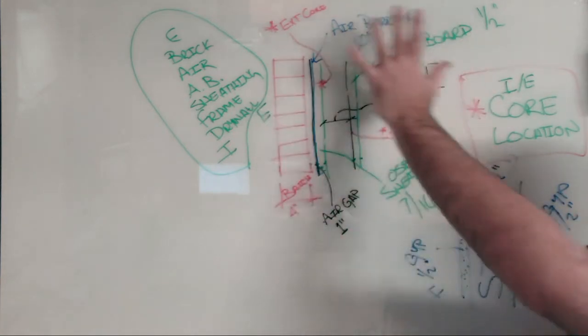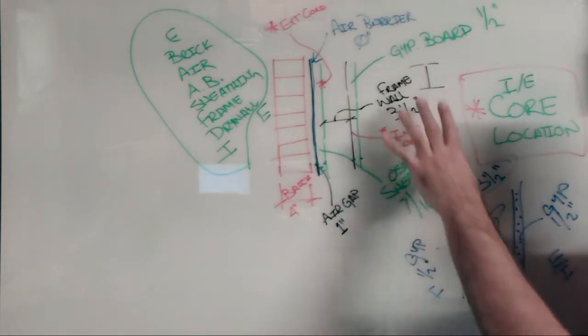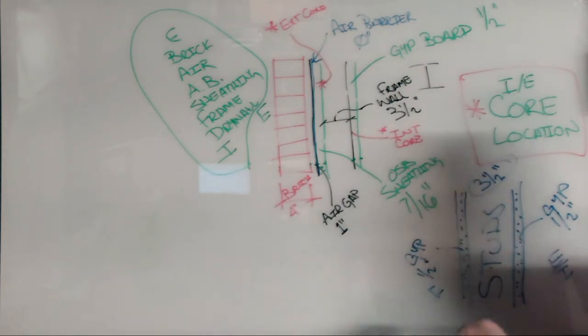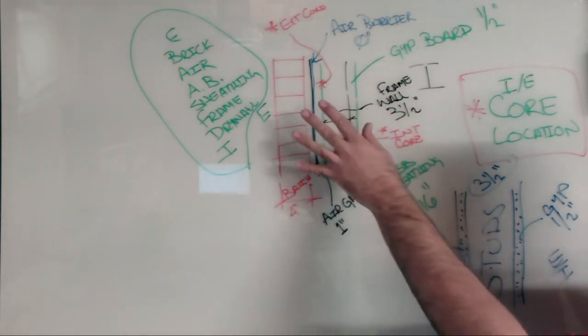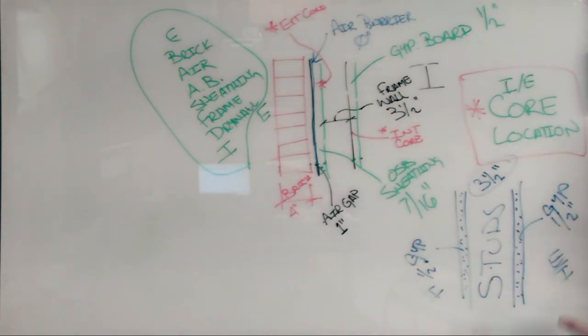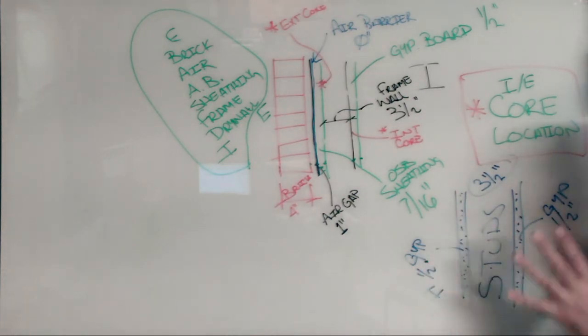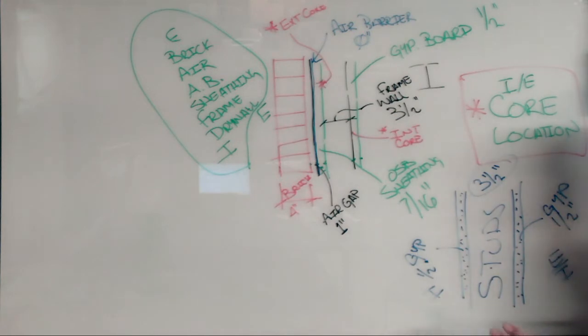So document this wall as the exterior wall. And while I'm up here, I'm going to go ahead and explain this wall to you real quick. This is our exterior wall. This is going to be our perimeter walls that go around the outside of our building. It's got the brick, it faces outward, and we're going to have our windows in this. This one here is going to be our interior partition. This is a wall that separates 2 offices or 2 bedrooms or whatever, but it is not exposed to the outside air. So this is simply an interior partition, which makes it a little confusing. We're still going to call it interior exterior, but that's just because the software needs to run that way.